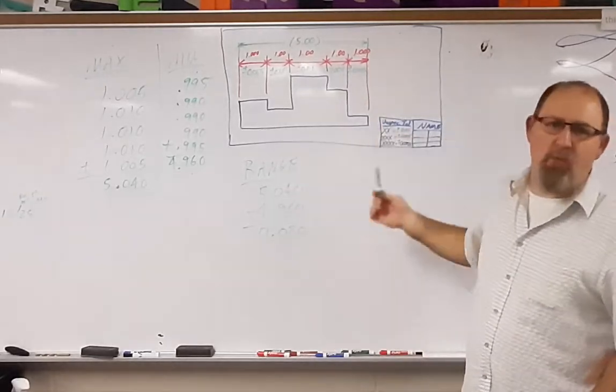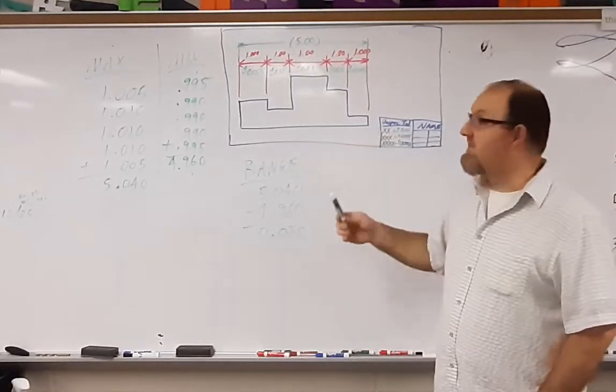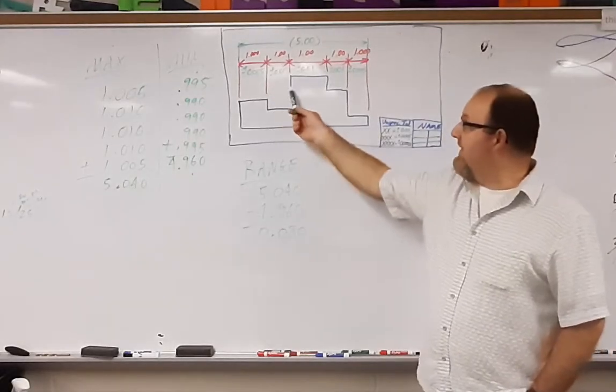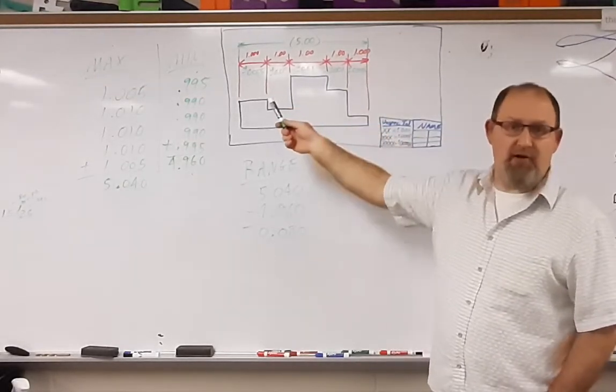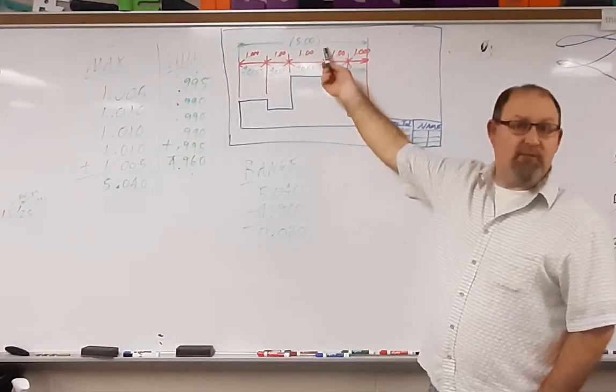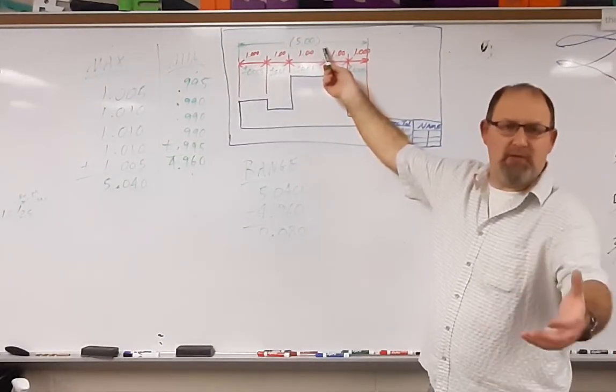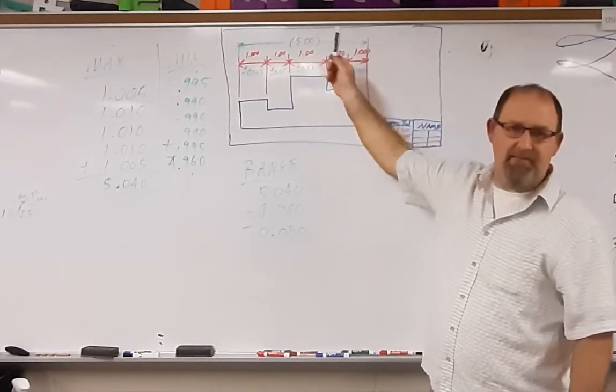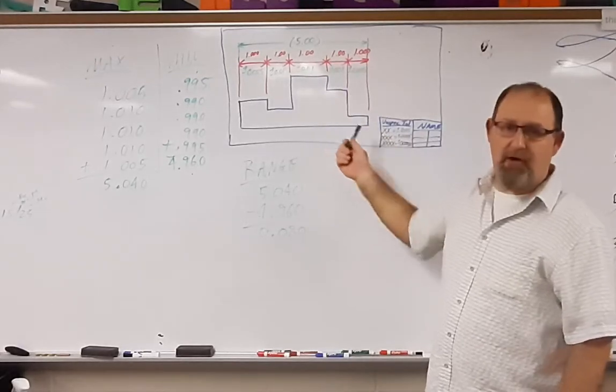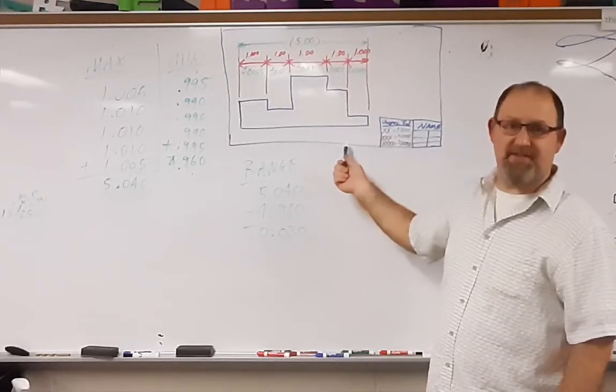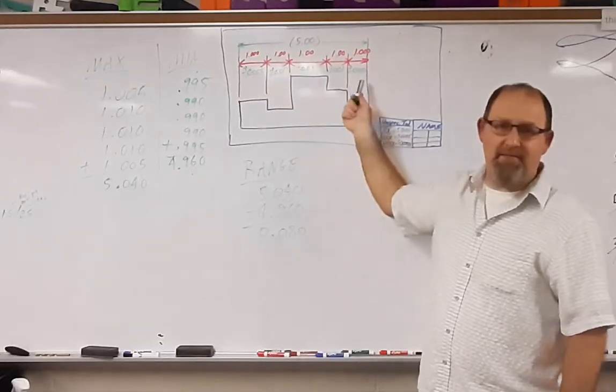So this here is one method for dimensioning. It allows you to have loose tolerances all the way across the board. It uses a reference dimension, which is just a quick reference for you, but this does not have any bearing on the actual part with the tolerance specifications. All that's required by the main dimensions.